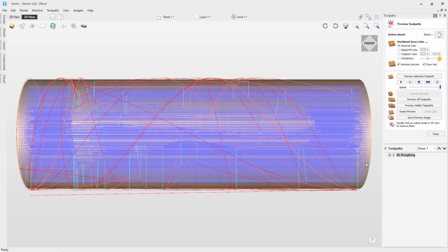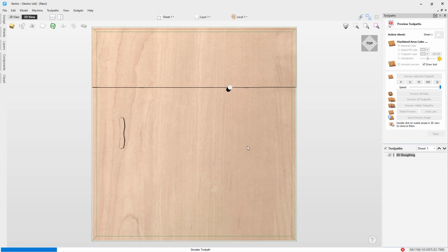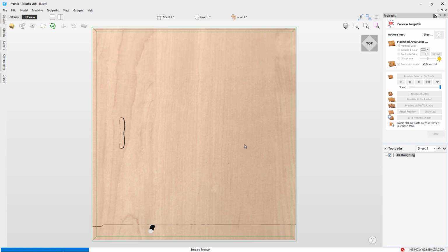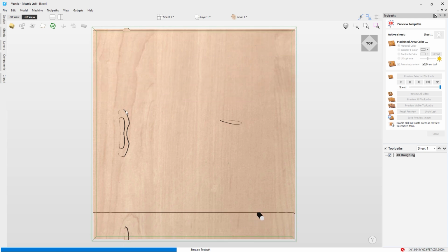And so you can see we're presented with our toolpath here on the left hand side, and we can look at previewing that. So let's click on preview selected toolpath to see what that's going to look like. You'll notice here that the software has actually unwrapped this job and is machining it as a 3-axis job, and then what it's going to do is actually wrap it around again. So you can see, as we spoke about earlier, that the software is using wrapped rotary.